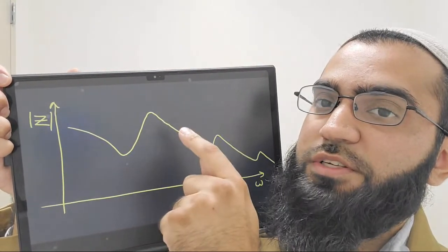This resonance and this other spot are not very different in impedance. So you'll actually have a huge contribution to your final wave. It's not just, I put a square wave into my transducer and it rejects all other modes. Yes, it will reject all other modes mechanically, but electrically you're also stimulating a lot of current at those frequencies due to capacitive behavior.